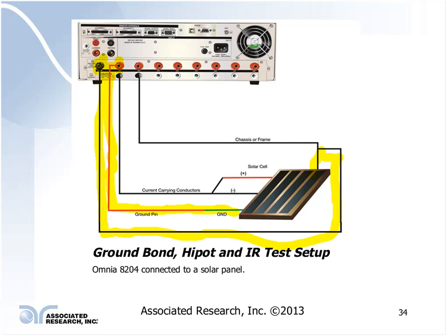So it would go through, close those relays, run that test, then it would open those relays and automatically flow right into my Hipot and IR tests. So then I can run this by shorting these two conductors and, again, returning on my chassis right here to complete the cycle. Then finally, let's say I was testing reverse polarity.